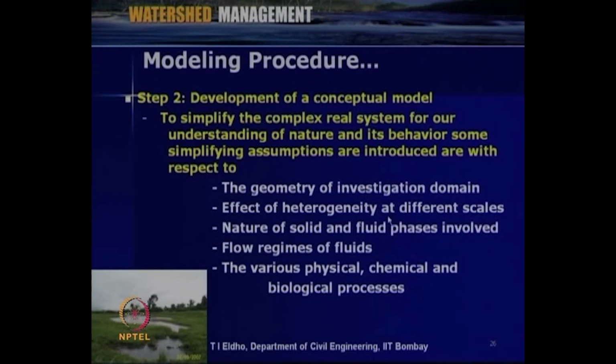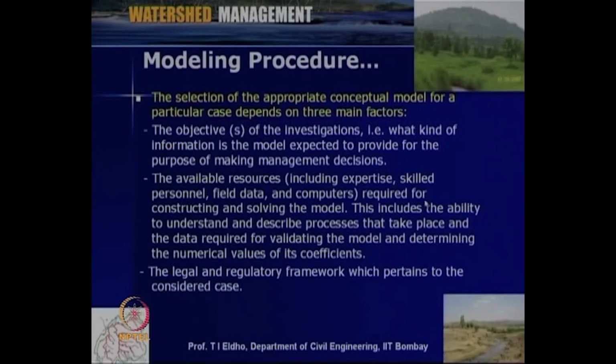Say, for example, the hydraulic conductivity varies from one location to another, but we consider various zones of average hydraulic conductivity. Then there is the nature of the solid and fluid phases involved depending upon the problem, the flow regimes of fluids, and the various physical, chemical and biological processes. So, this way, in step number 2, we develop a conceptual model.